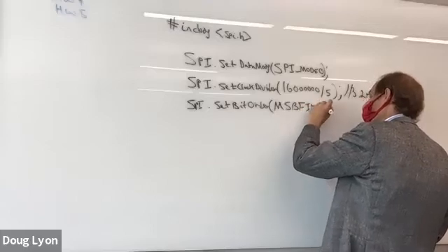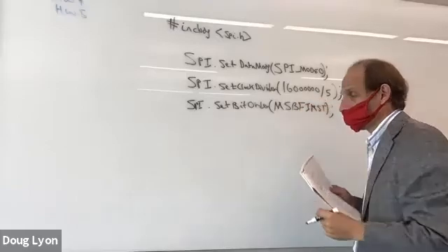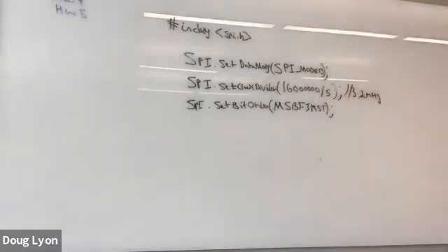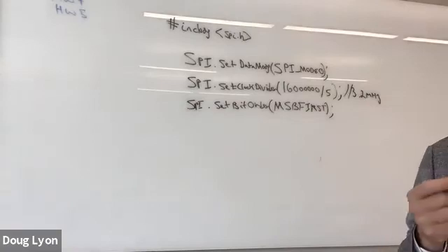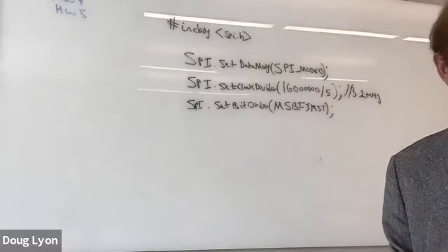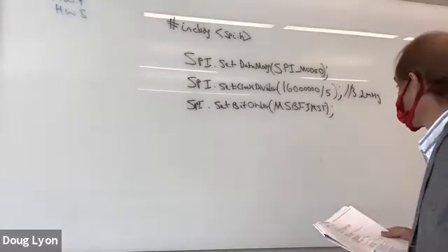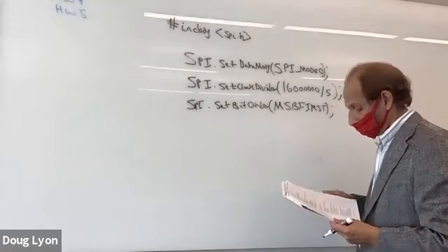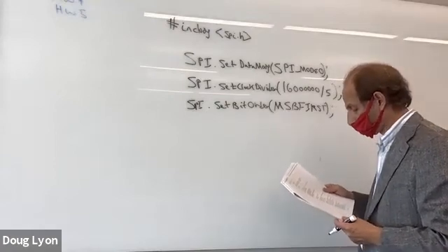And that's important because we're shifting the bits out one at a time, and we have to know which bit is coming first, the least significant bit or the most significant bit. We do the most significant bit first because if we decide that we're only going to have an 8-bit DAC instead of a 12-bit DAC, we may only want to shift out 1 byte at a time. So we might just shift out the 8 most significant bits and let the rest go to 0.